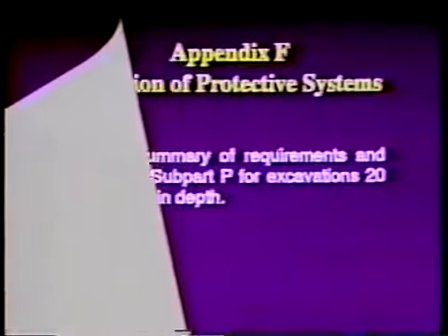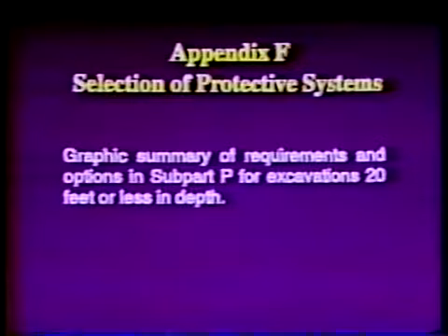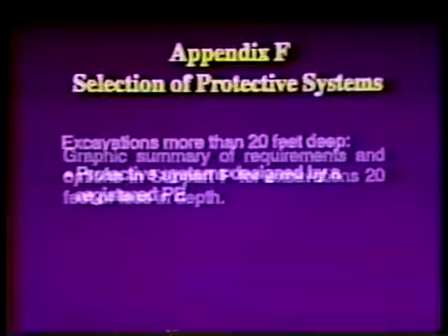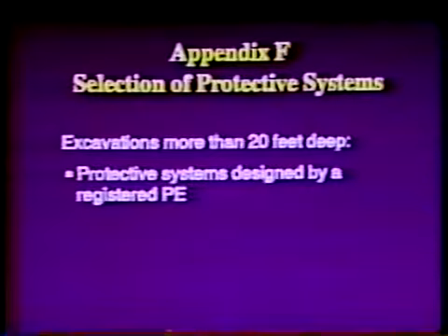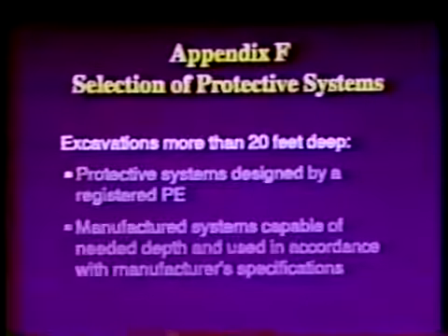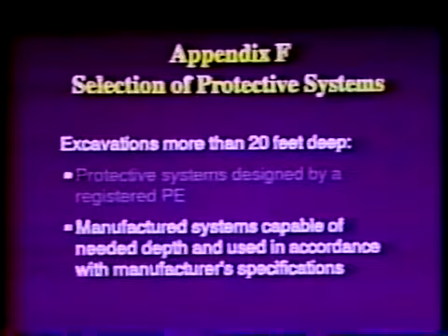Appendix F presents a graphic summary of the requirements and options in Subpart P for excavations 20 feet or less in depth. Deeper excavations require protective systems designed by a registered professional engineer or manufactured systems capable of the needed depth and used in accordance with manufacturer specifications.